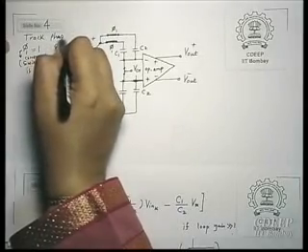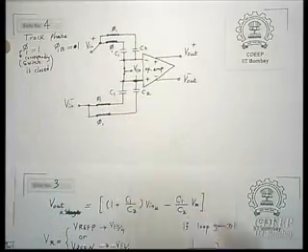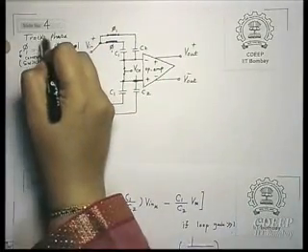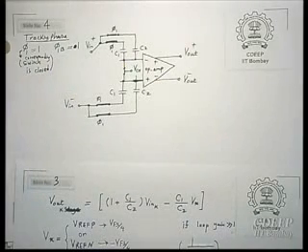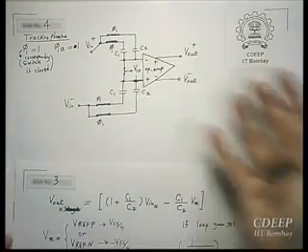In fact, it is tracking, it's still not holding, because if the input changes, that also will change. But in this tracking phase, if you notice, the two inputs of the Opamp are shorted together. That's why it doesn't have offset compensation. What we could have done, the correction you can do, is the same as what we had. You open the inputs, and then you keep the Opamps in the unity gain feedback mode. Therefore, now you will have offset also stored on the capacitors. Same thing that we had before. Here they have not done this. This is a short circuit and the Opamp is in the open loop mode.